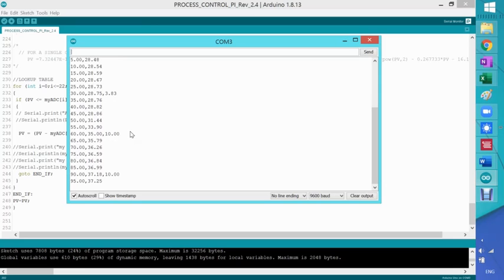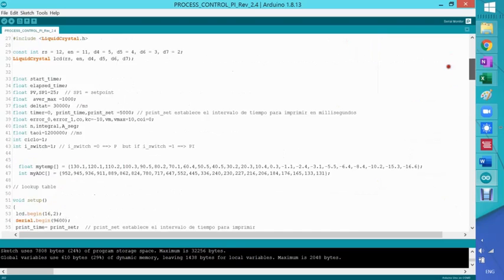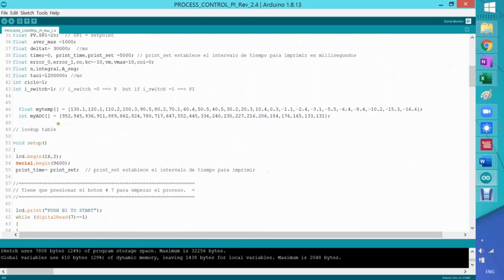For example, on my thermistor, let's see, the ranges that I have from the data that I got is this. Let's go here. What happens if the ADC goes, I don't know, like 1023, a number higher than 952? Well, you gotta write code to handle that. Obviously, you will have something kind of weird. The same will happen if your ADC is less than 131. You see, if you are beyond those limits, then you are not doing interpolation anymore. You're doing some extrapolation. So that would be something else.